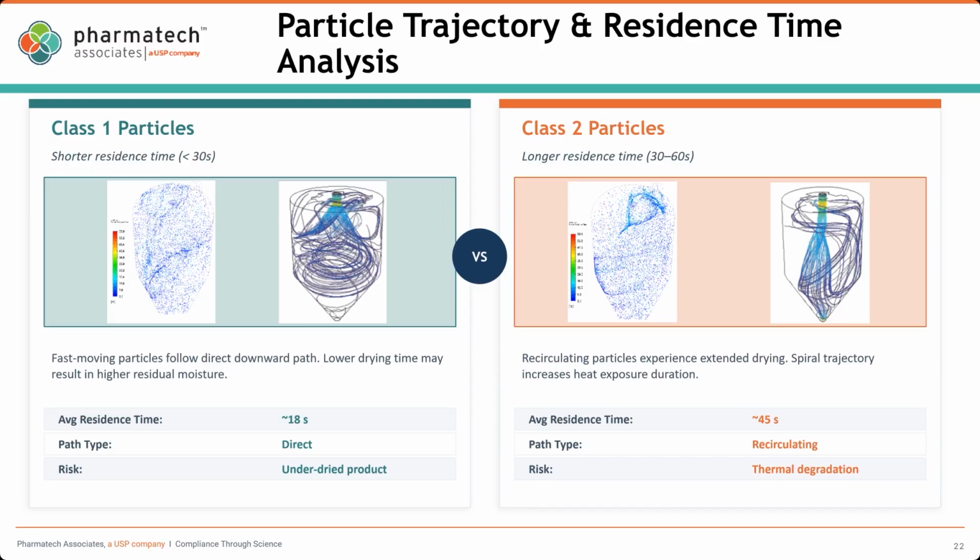In the D90, with a longer diffusion length in the particles, they stay wetter. If you're measuring the particle size, the degradation and the residual solvent content, the profile from D10 to D50 to D90 would be very different. All of this would be predictable by the models, and you can see it in these examples. And then we can start running some what-if scenarios. What happens if I change my temperature? Next slide, please.